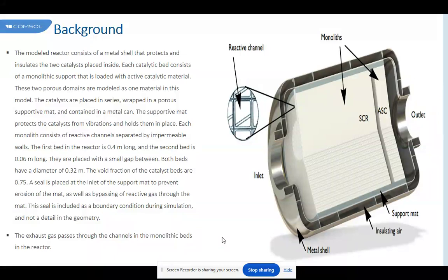It is also important to mention that both substrates differ in their void fraction but have the same 12% by volume of washcoat. Consequently, the washcoat represents a higher percentage of the solid volume in the 900 per 2.5 monolith than in the 400 per 6.5, and this difference in washcoat fraction changes not only the thermal conductivity but also the thermal mass of the reactor.